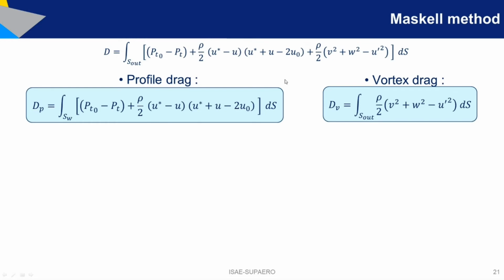The newer part is this one related to the transverse kinetic energy, and this is called the vortex drag. And this requires integrating the transverse kinetic energy in an infinite survey plane that's placed behind the body. Notice that this is wake reduced and this is not yet wake reduced. It requires measuring parameters on an infinite surface, and this is a problem because for our practical applications I will really need to measure or find a way to compute this only reduced to the wake.